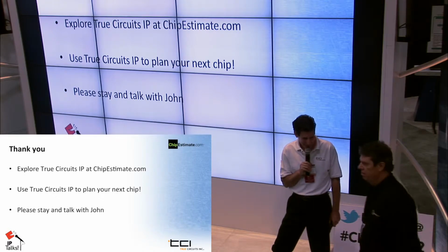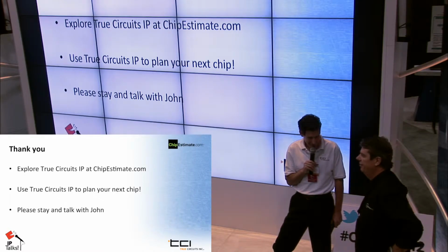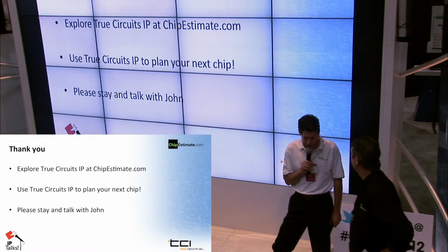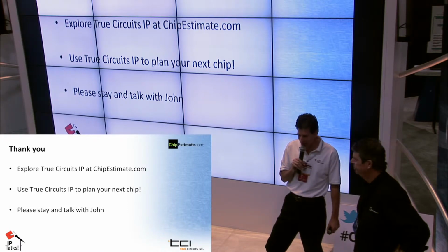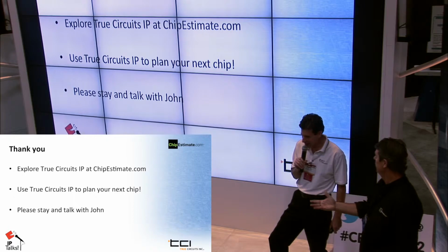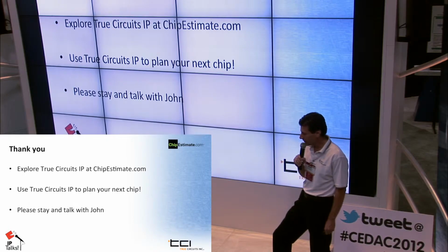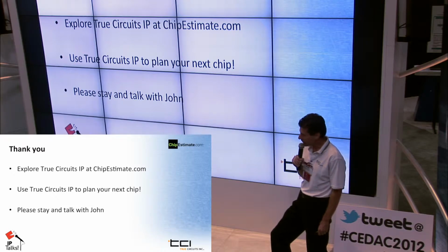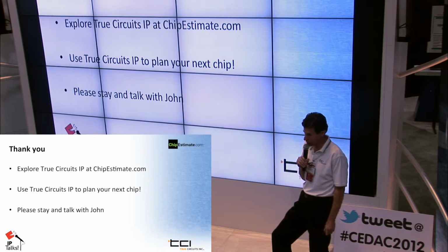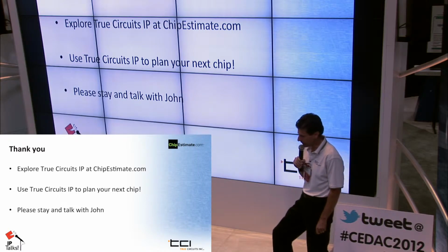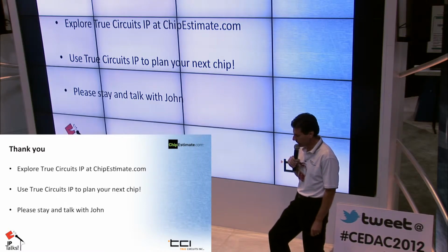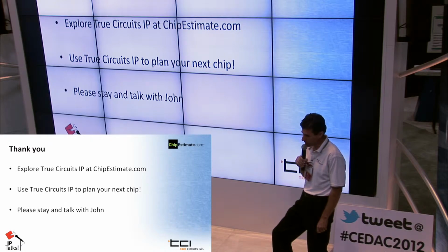Go ahead, Sean. What is the importance of low jitter for PLLs? Well, jitter is a key parameter for PLLs. Jitter could impact in many different ways depending on how the PLL is used and what it's used for. PLLs used to generate a core clock for a processor would be impacted in terms of setup time.